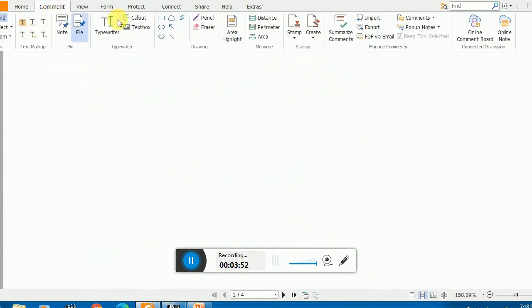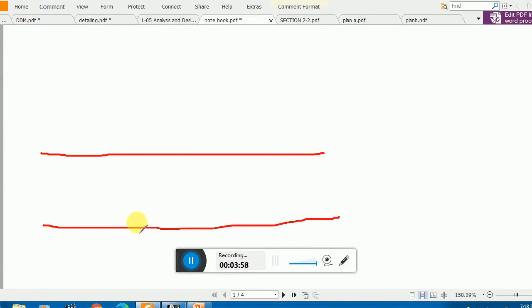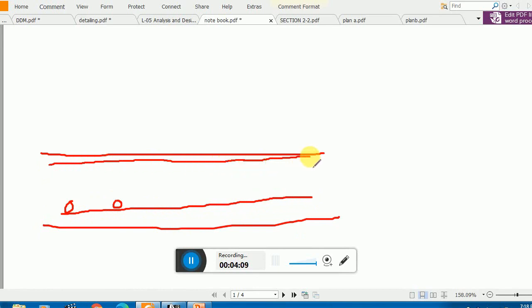First of all, let me show you, this is my slab system. First I calculate and provide the bars in the bottom, then the transverse bars in the top, then I will calculate the negative bars. Okay, and then I provide the crossbars for those negative bars. So first you will see these bottom bars.